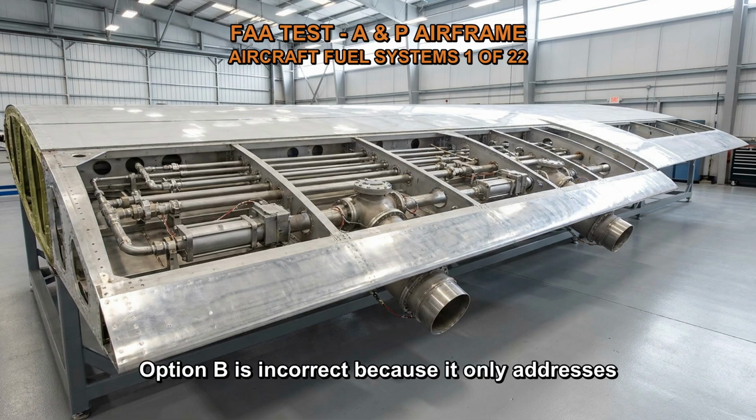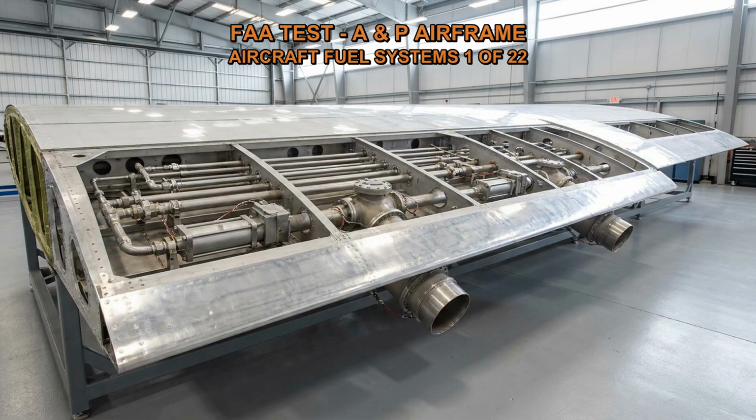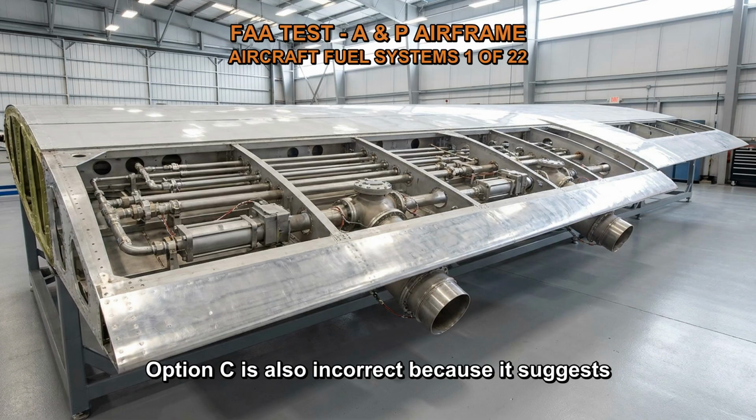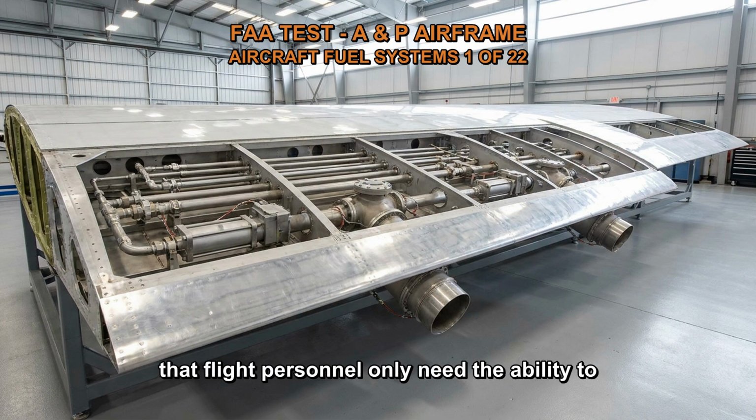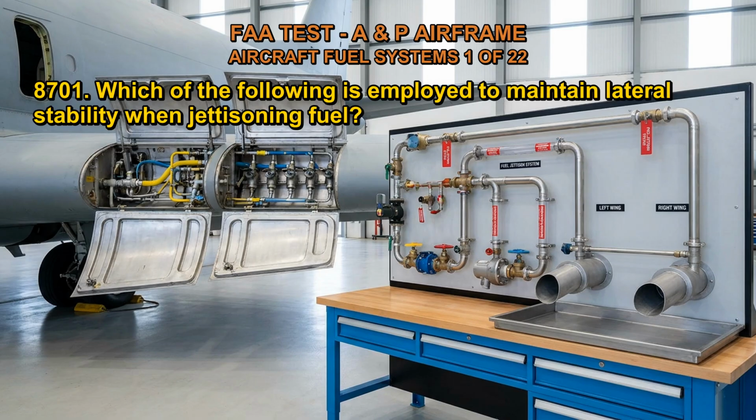Option B is incorrect because it only addresses the need for fuel to discharge clear of the aircraft and does not mention the need for flight personnel to be able to close the valve at any time. Option C is also incorrect because it suggests that flight personnel only need the ability to close the valve, but does not address the need for the fuel to discharge clear of the aircraft.